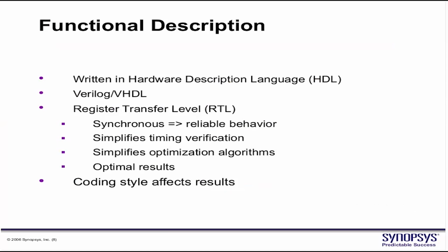Now first we start with the functional description. It is written in a hardware description language, Verilog or VHDL, or we also call it RTL, register transfer level. Most of the designs which you will practice hands-on will be synchronous. Synchronous means there will be a clock. All the handshake between different parts of the design will be based on a clock signal.